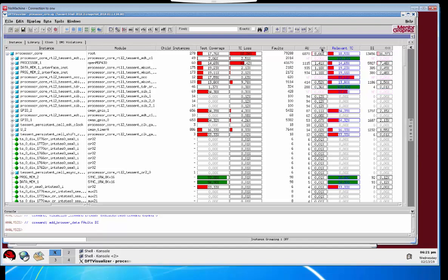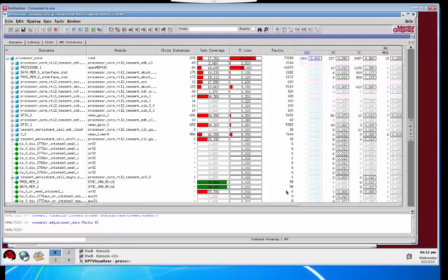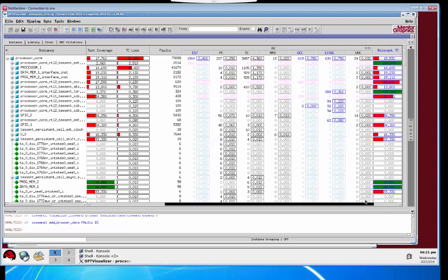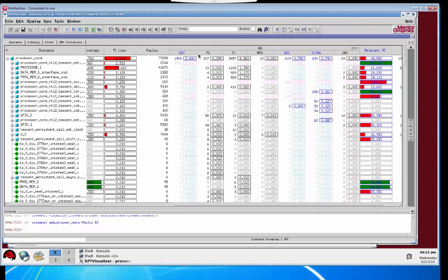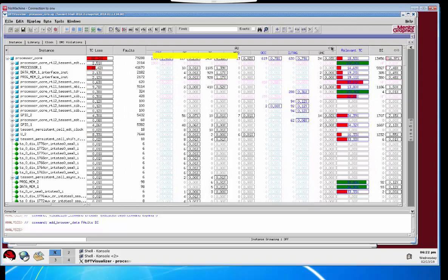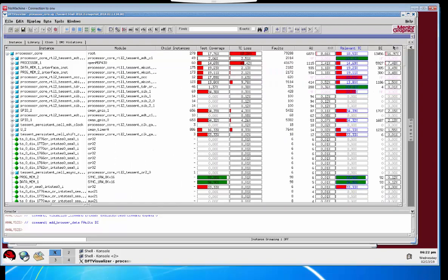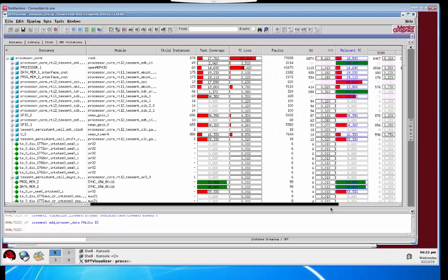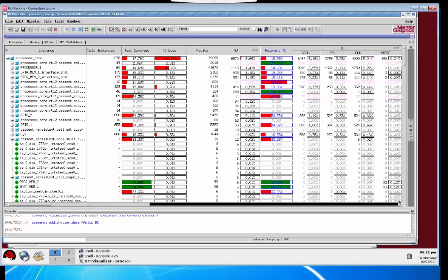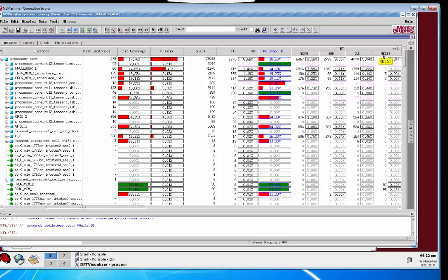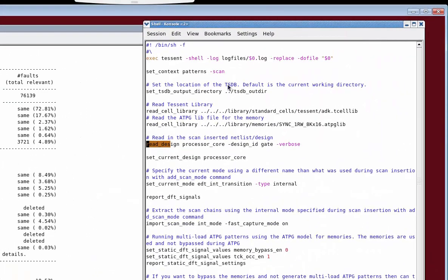And you can see this little expansion, this little two-way arrow here. If you click on that, we can expand the AU category and show all the subcategories. And here you can see where we have the OCC and IJTAG instruments, which is what we looked at previously in the command line view. So we can collapse that. And then you can do the same thing for the DI faults, for instance, detected by implication. And again, here's the MBIST related fault. From here, we can go ahead and create the patterns.